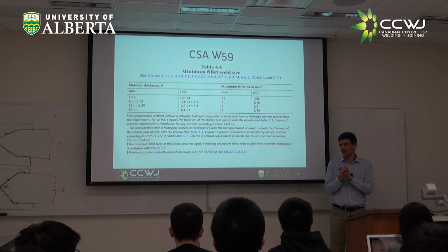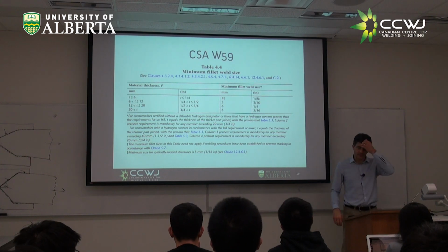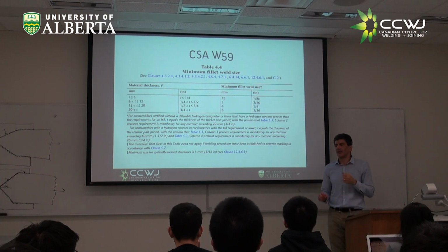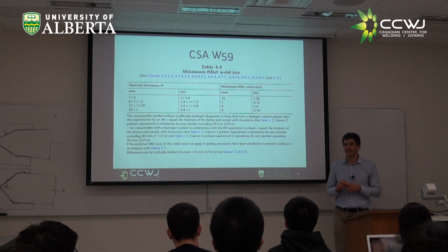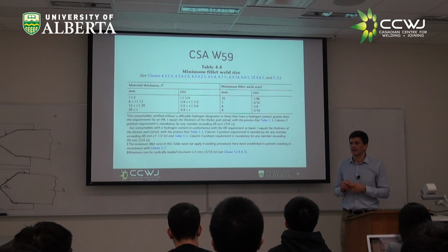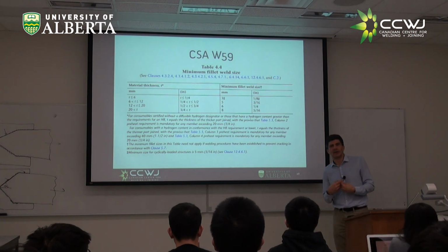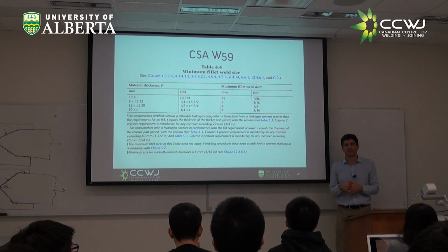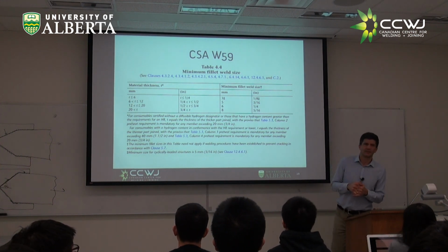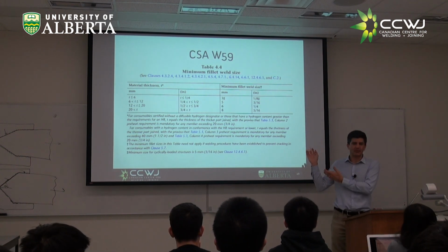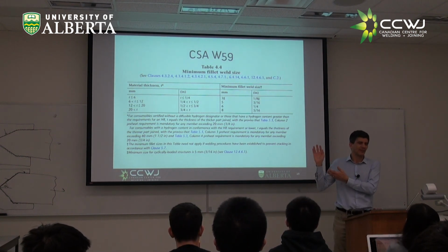Actually, I thought of that, but then when I looked into practical tips that you can find on the internet, they mention it. Anybody want to tell me what problem I would have with too small of a weld? No, actually, a small weld would give me less distortion than a big weld. Imagine I could make a 1 millimeter weld. Why shouldn't I do it? Right, yes, you would have cracking, because in the end, the standard tries to prevent you from being a fool. But there's a limit.